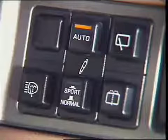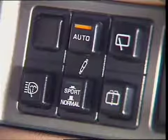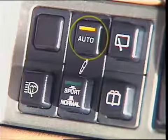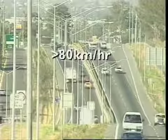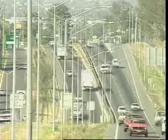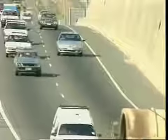The ECU allows different modes of operation according to a selector switch on the dashboard. In the auto position, the dampening effect at the front wheels is increased at road speeds above 80 km per hour. This improves vehicle stability at high speeds. The rear shock absorbers stay at their normal setting.